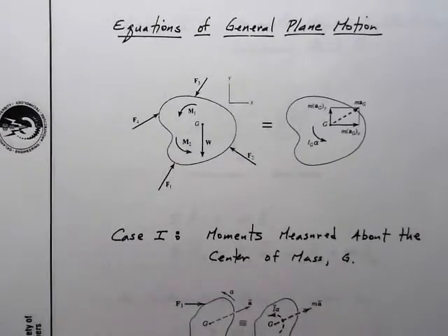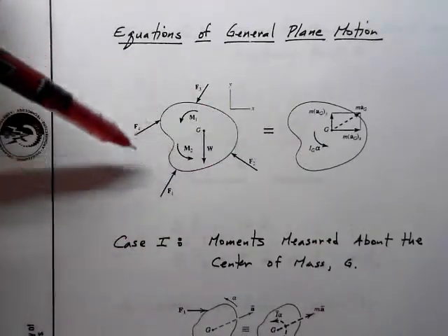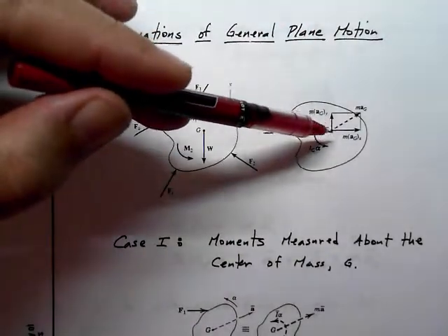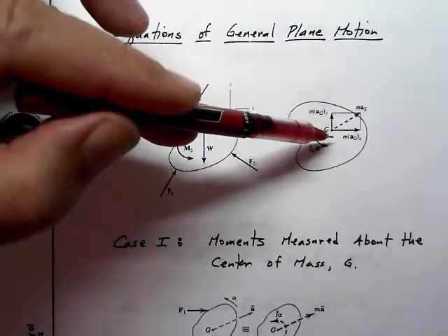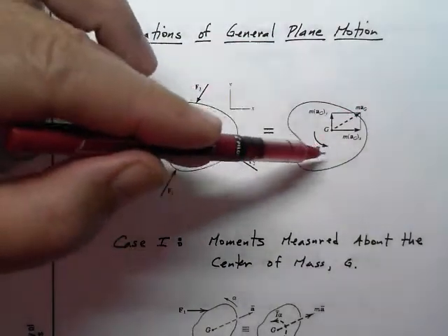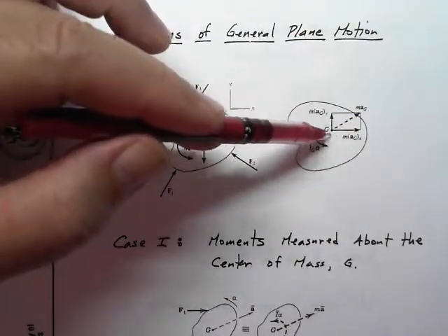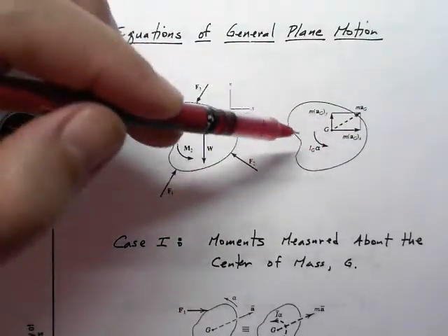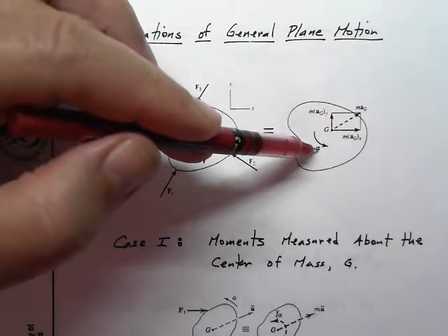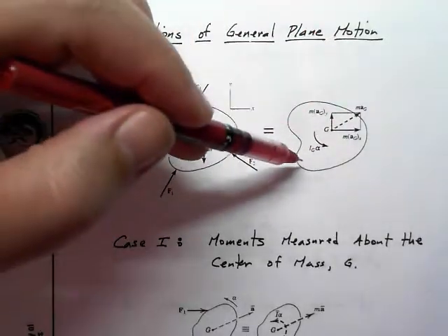Okay, we're not going to have a lot of new equations out of this chapter, but we're looking at a vector picture of relating forces and moments to various kinds of accelerations. Because we're talking about planar rigid bodies, we now have the possibility of acceleration in the x, acceleration in the y, therefore having a total vector acceleration. But in addition, we have the possibility of alpha. These quantities are mass times acceleration, something that deals with how much mass we have times its linear motion. The quantity on the right hand side of our equation that we will be adding in this chapter is moment of inertia, a measurement of mass distribution, times the angular acceleration. So we have both forces and moments equal to mass times acceleration and I alpha.